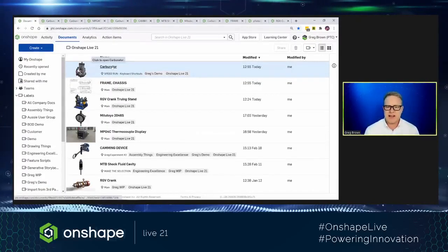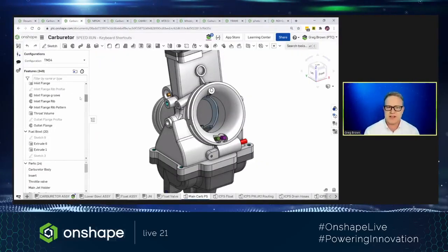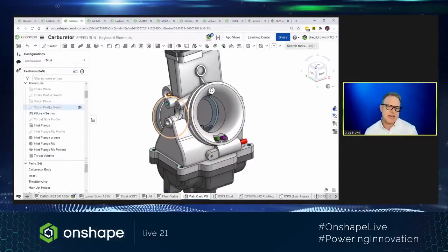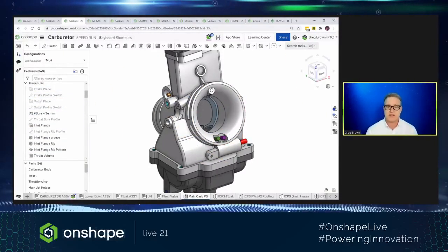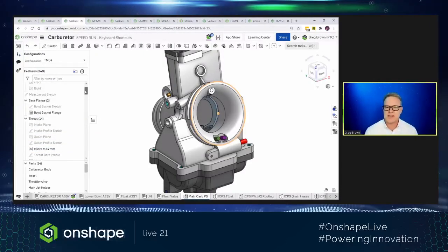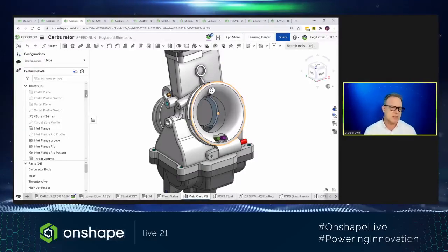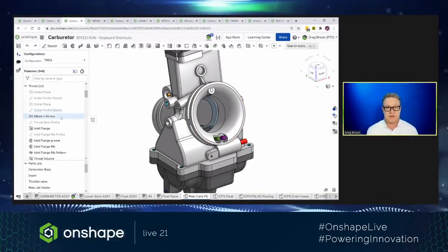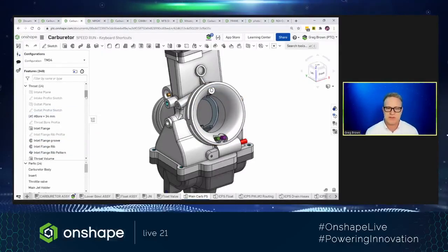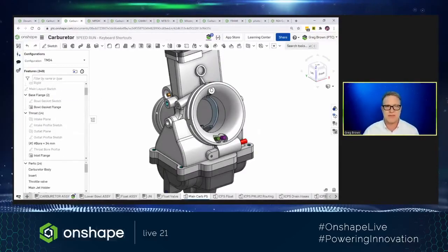And let's talk about naming. One thing I love is that since Onshape is a modern application, it allows for proper naming of everything, long names, capitalization, spaces, even apostrophes. It's amazing how this really helps bring things to life. There's really no excuse to having long lists of features called things like extrude 1, extrude 2, extrude 3, and so on. So go on, take the extra few seconds to name things properly, and you will not regret it when you and others come back to edit.